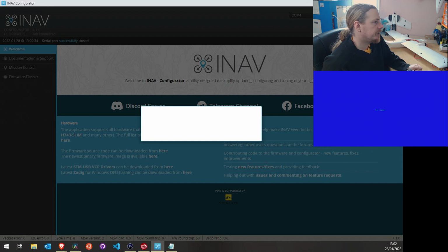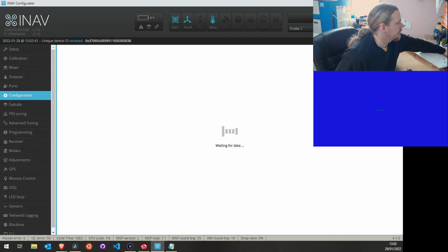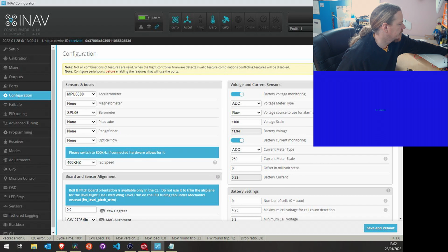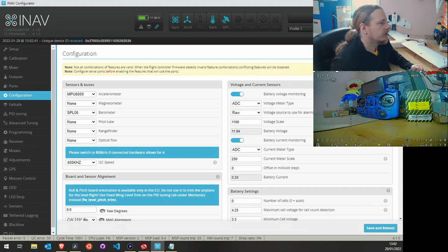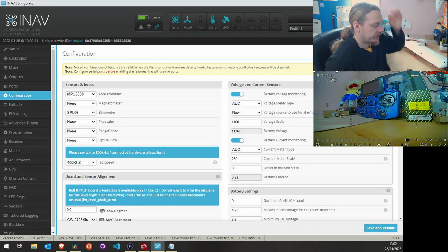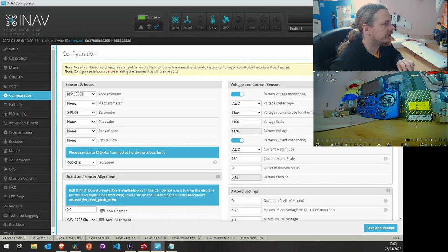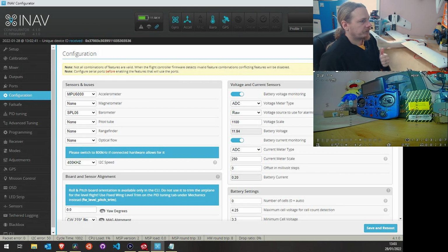And we shouldn't get any picture. There we go. So let me retune. And there we go. We're obviously on a different channel because I needed to retune the VRX. So SmartAudio is working. So we know that everything is good to go now on the video side. Our OSD is fine, our picture's fine, and our SmartAudio is good.